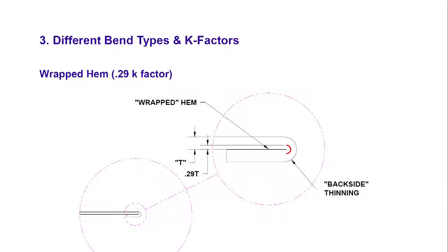So, we see here a completely bent over 180 degree bend. Can we actually make it flat? Under some conditions, yes, depending on the softness of the material. The reality is that usually, though it is not easily visible, a small gap will be left there. In this case, it is given approximately 1/4 of the thickness, a little over 1/4 of thickness. When I showed you the small cover for the power supply unit, it is very thin. To make the edges stiff, they have bent them over, formed something a little like a bead. Technically that is not the name, but the whole thing is completely made flat like this.